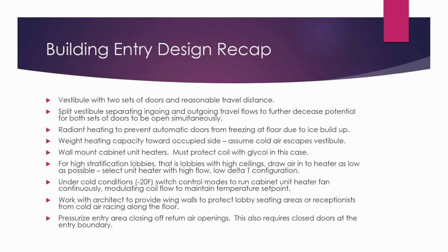Weight heating capacity towards the occupied side. Assume cold air escapes the vestibule. So don't think that a lot of heat in your vestibule is the way to go. It's much better to heat outside the vestibule. Try to pick that cold air up that's flowing along the floor.